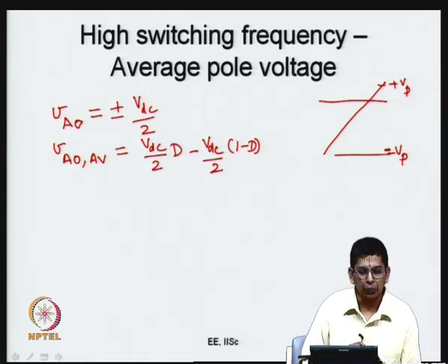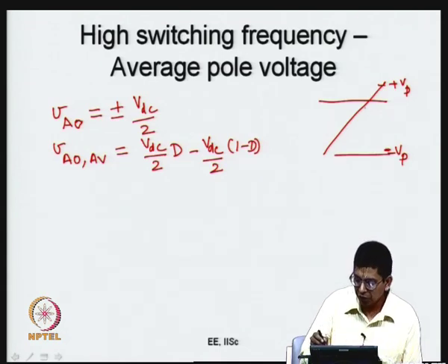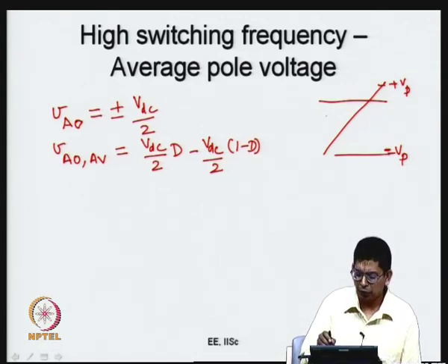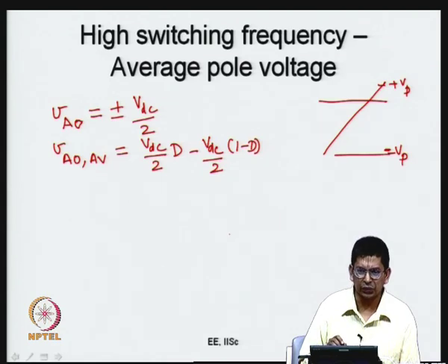So, what do we do when we are switching? Now, I have regarded the modulating signal as a DC. Why? Because we are looking at a very short interval of time. It is much shorter compared to the fundamental cycle, and therefore, you can ignore whatever variation that you have in the sinusoid, or you can take it as the sampled value of sine. So, it is a flat line here. You compare this sampled sine wave and this carrier.